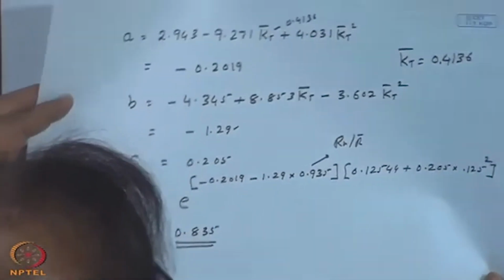The reason is it is operating at a T minimum of 20 degrees, considerably lower than for the process heating system that we were using earlier, which was at 60 C. And there is logic to say that non-dimensional utilizability phi bar will be higher at lower kT bar.